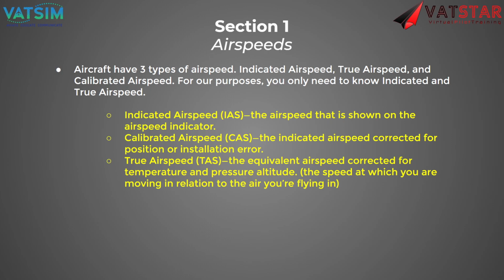And another quick question. To calculate ETA, do you use true airspeed or ground speed? For ETA, you want to use ground speed, because that's the speed at which you're moving in relation to the Earth. So that's what's critical.